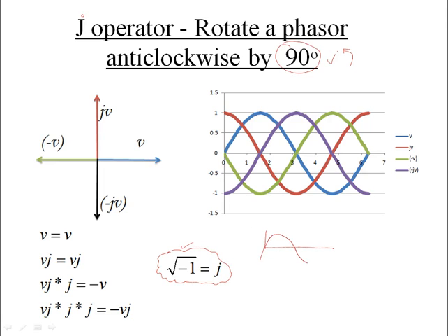So this is my voltage vector V, right? And the corresponding phasor will be like this. If I rotate this, right now this projection is 0. If I rotate it to this point, I'll get the maximum value. And if I rotate to this direction, I will get 0. And if I rotate in the negative direction, I'll get the negative maximum, like that.